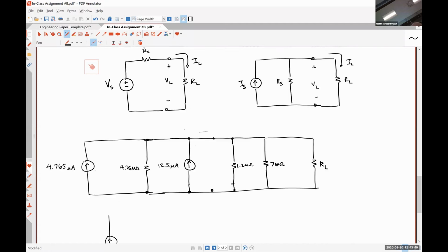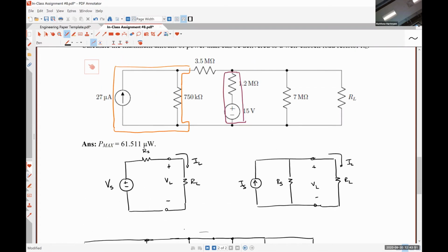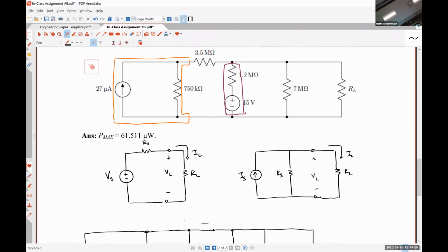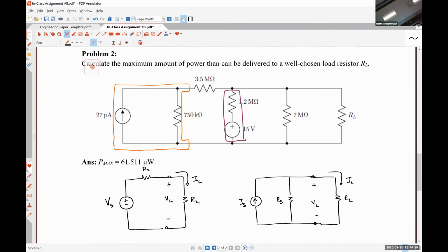Okay, so the voltage source, if the positive polarity terminal is on top, the head of the arrow should be pointing to where the positive polarity terminal was. So the arrow should go from negative to positive. So that's why this guy is directed in that way. Now before, when we did this transformation on this guy right here, the head of the arrow is on top, so that's where I put the positive polarity terminal. And then when I switched it back, it would maintain its same direction. Okay.